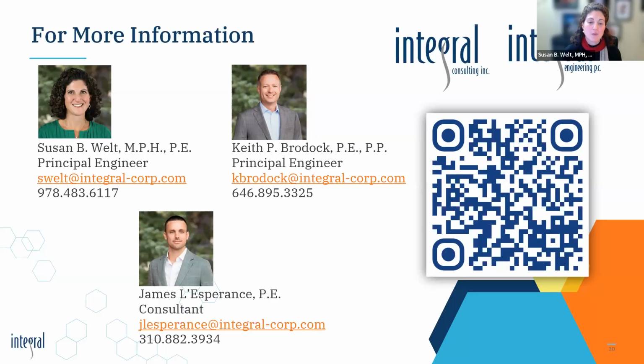The other thing that we've also seen is with warmer conditions, we may have more condensate occurring in the piping of the systems if we're doing a traditional SSD or SVE type system. So we have to think about how to design the angles, how to put in more knockouts, how to collect that water, and what to do with that water, because of the different temperatures being created by warmer conditions. So lots of things can come into this, thinking about what the building is and the conditions, and the future, not just now.